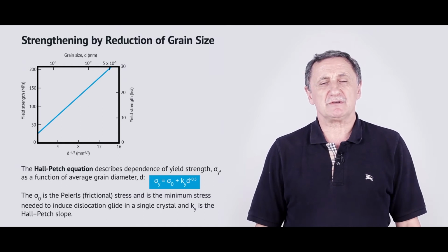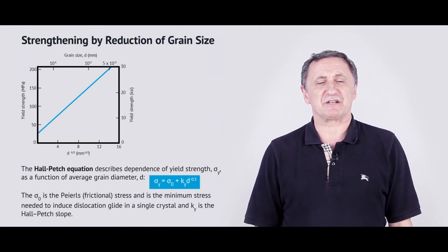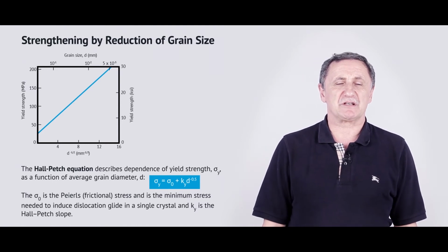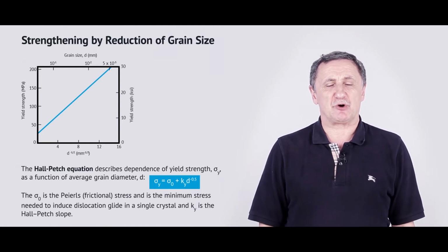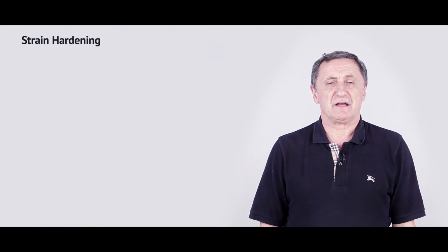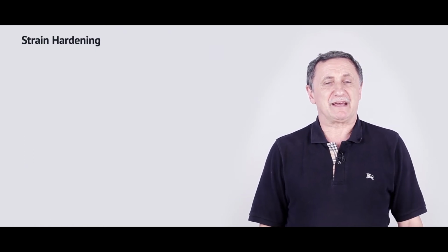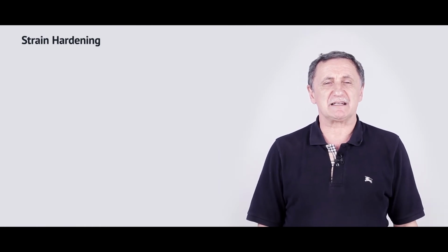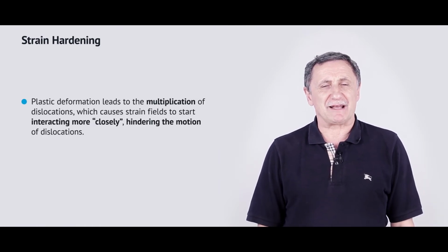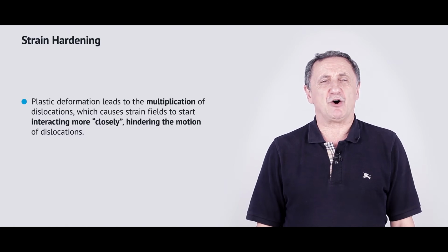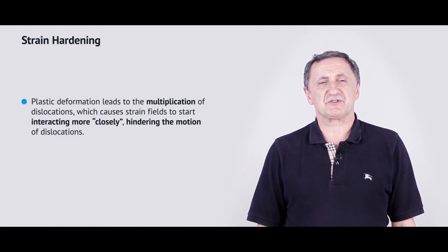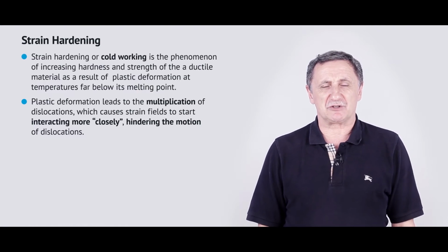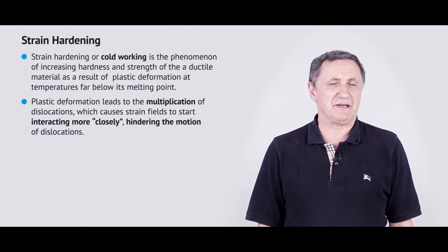So now we know that the smaller and finer the microstructure of your grains, the higher the mechanical properties you have to expect from this material. So now, how can we control the grain size? It's very, very important. But before we go to that, the other strategy for making our material harder is so-called strain hardening. And this approach is extremely interesting, as for me.